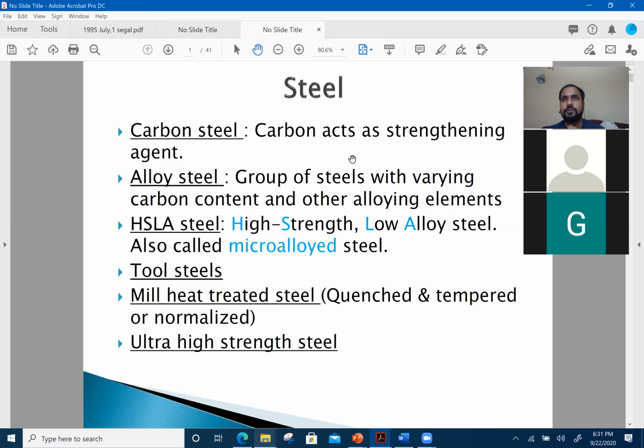Once you go into the details of this phase diagram, you'll hear things like proeutectoid cementite, proeutectoid ferrite, and pearlite phases. That just shows you that we are on the right side of this region and we are forming pearlite in that region. So yes, it forms there. We just didn't go into details of that part here. But I really like your bainite question. I'm going to look into that. What I had seen looking at different microstructural components is that bainite forms underneath the nose of the TTT. Yes.